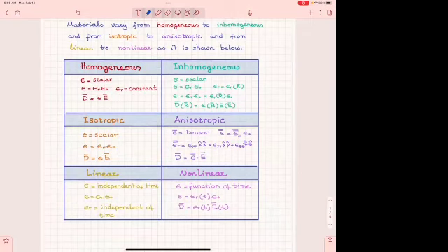So what we call homogeneous. Homogeneous we call a material where epsilon is a scalar, first of all, and it has a relative dielectric constant, epsilon sub r, which is this one. And this is constant everywhere. That's why we call it, well, it's a constant because it's a number, but it does not change in the space of interest. And it does not change with time, it does not change with any location in the material, nothing. So that is called a homogeneous material.